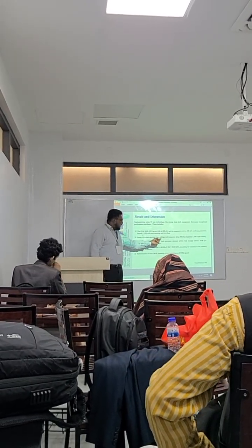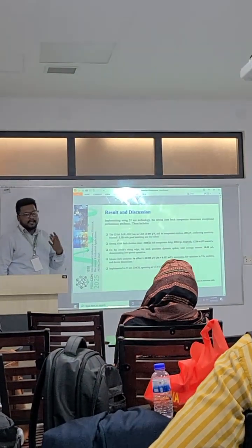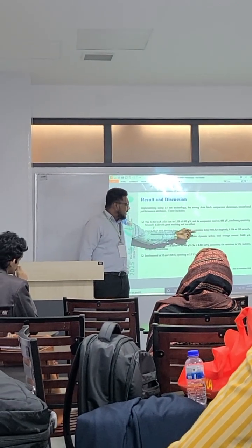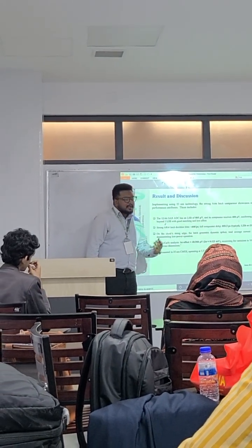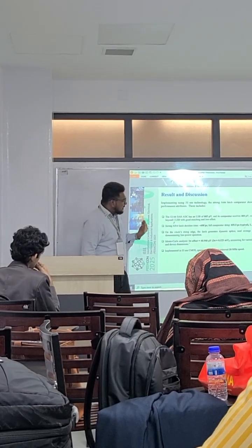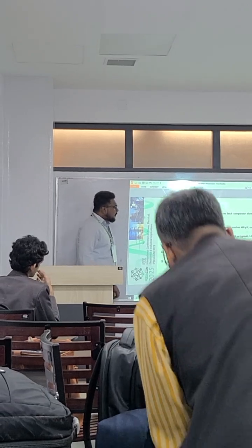The propagation delay here is 600 picosecond, and the whole comparator, along with the preamplifier I showed previously, has a propagation delay of 855 picosecond in the typical corner. And in the worst corner in the PVT analysis, the delay is 1.226 nanosecond.